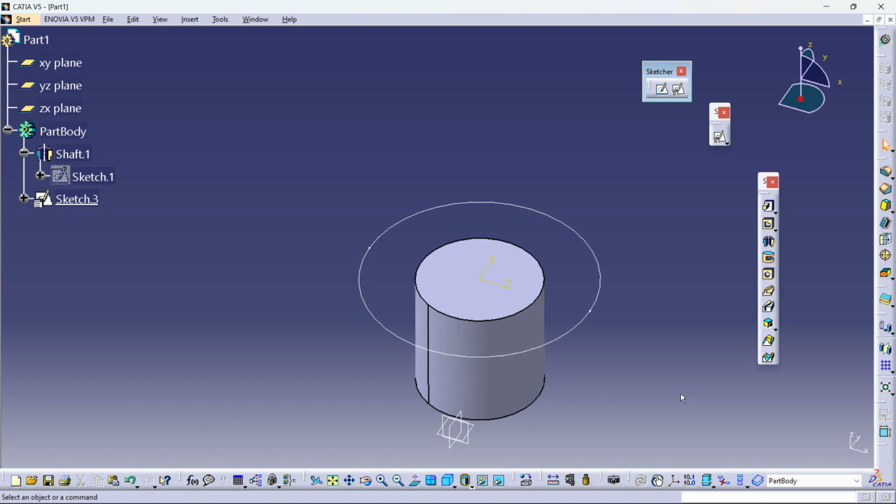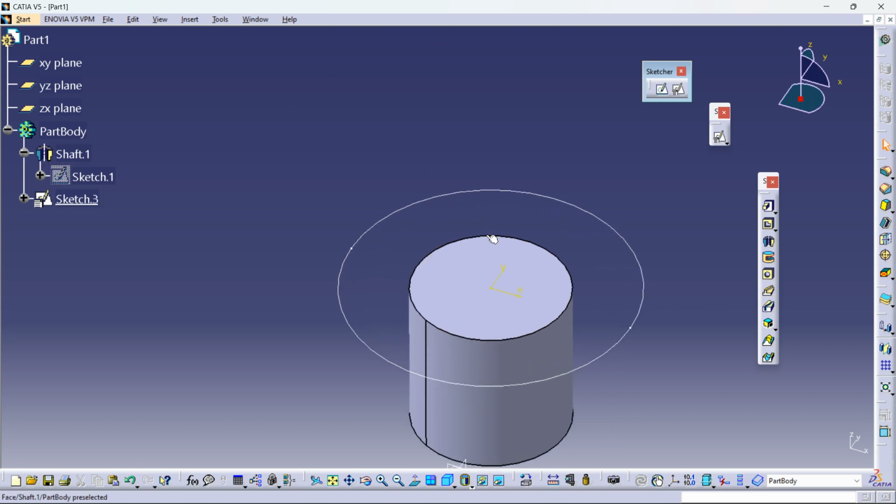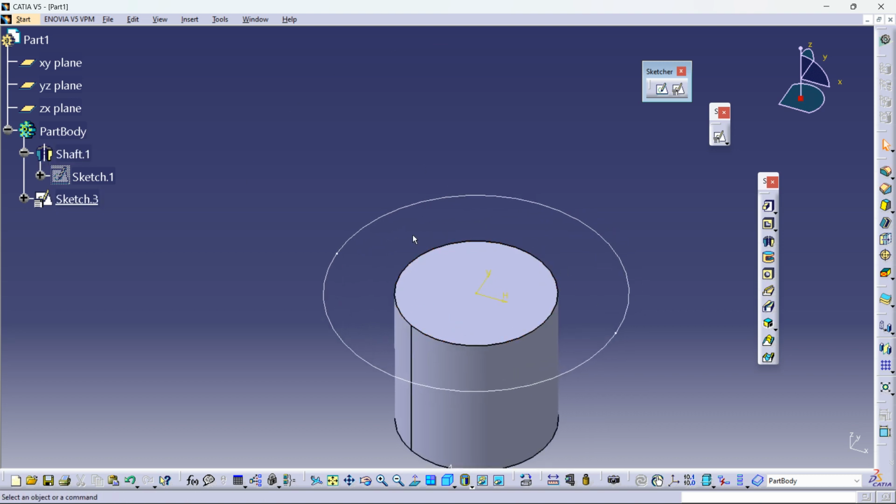It is for circle. It is always in diameter, and for arc, it will always be in radius in SolidWorks. You see, this thing is understood, right? Constraints and all, everything will be under this sketch, also the sketch itself.